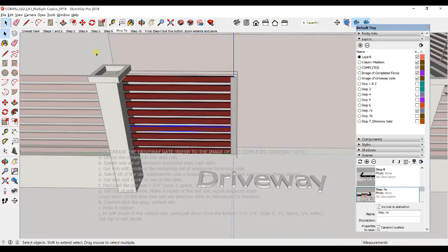So we can just do a huge bounding box because when we are in edit mode, the only thing it's going to pick up is anything in this grouping or this component that I am editing. So even if I do the right to left bounding box that picks up everything, you know, even if you hit just the tiniest little bit, it should pick up everything in its path. Because you're in edit mode, it's not going to pick up anything that's outside of this grouping. Another reason why we do groups and components.